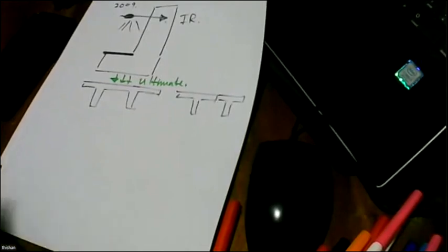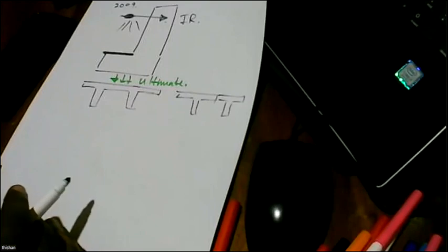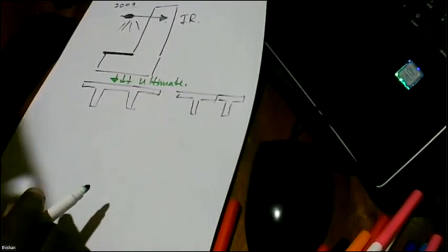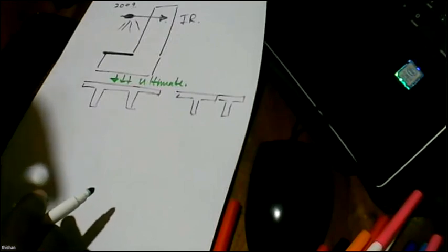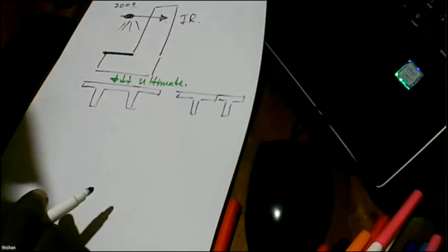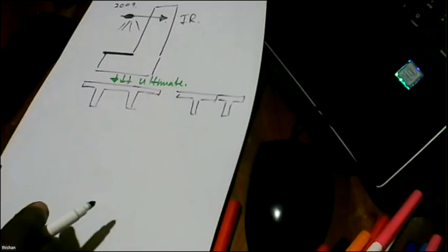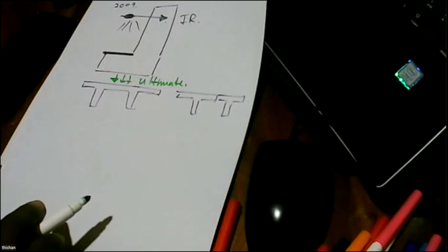We just did some strengthening because we had to look at the durability. The reason is, the moment the beam is cracked and some steel has yielded, you always have to look at the durability problem. But as far as service loads were concerned, we did not have a major problem.